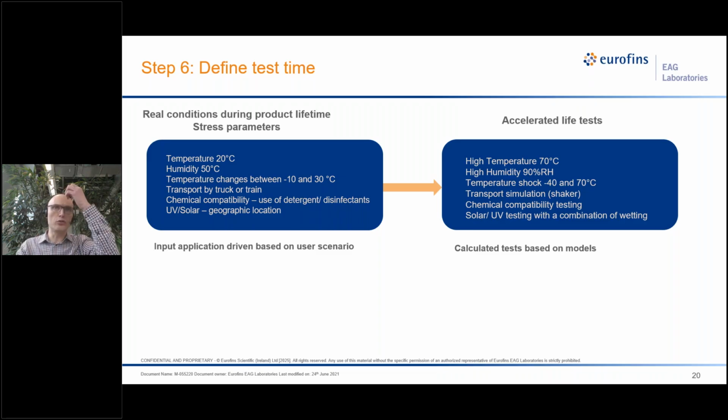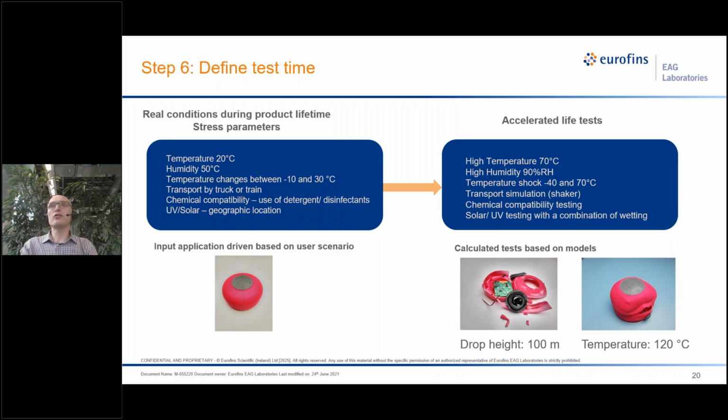And I want to show you two failure mechanisms which are not realistic. We stressed a Bluetooth speaker by means of a drop test, and if the drop height is too high, the enclosure will break after one drop. And the second one is the temperature test. If we stress the Bluetooth speaker at a temperature which is too high, we introduce a deformation of the enclosure, which is also not a realistic failure mechanism.